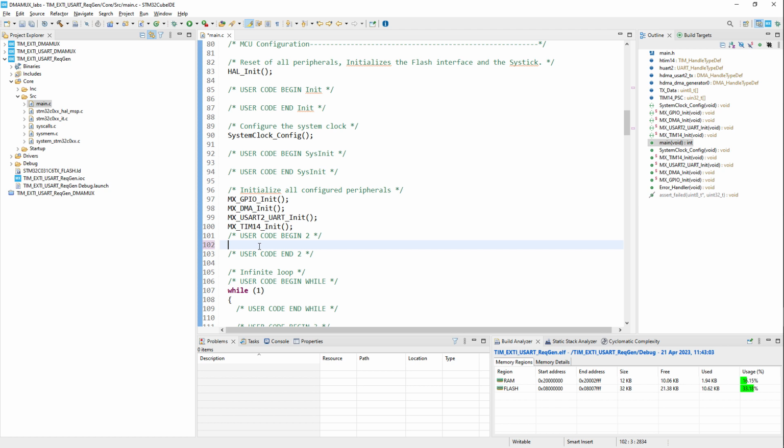So we'll start from enabling the request generator, which we configured, so request generator 0 in our case. It is available within the DMA library, but its extended version, because the DMA multiplexer does not exist in all of the STM32s. So it will be in this extended part. And we've got already the proper function by control space and argument. This is the first one, because the second DMA channel is used for USART 2. The first one is really the DMA generator.